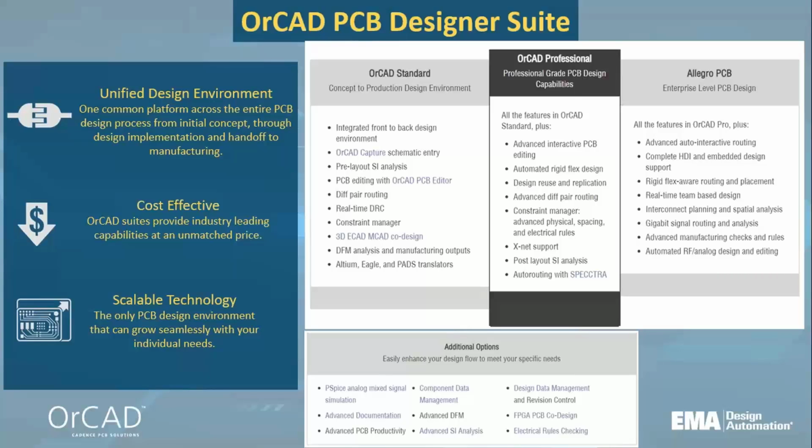Another question, if I translate a PADS PCB design into OrCAD with the existing schematic, can I cross probe? Yes, you will be able to cross probe between those two files. Do the design constraints in PADS also get imported into OrCAD? It does not. So you're going to have to reset those up. And that's always been a problem when you go from one tool to the other. The constraints do not come with it.